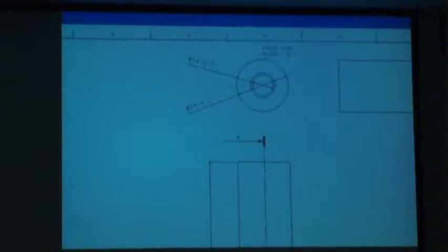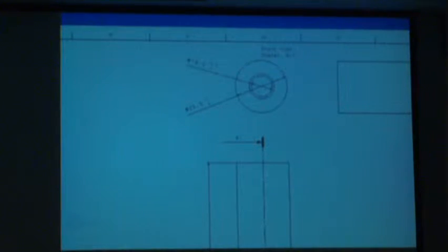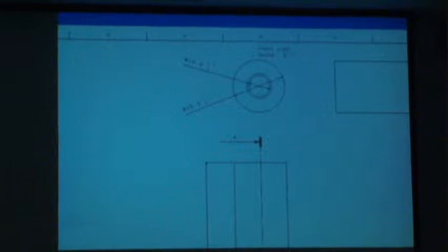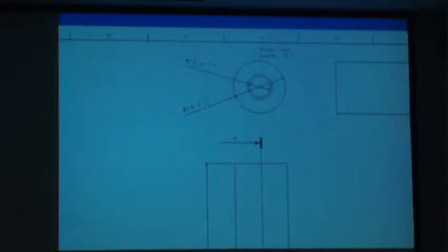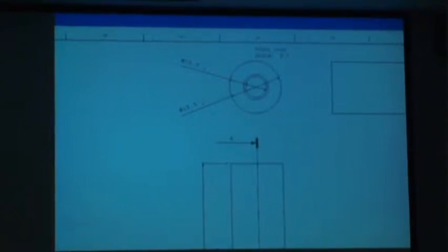And depending on what the part is for, you'll have a different tolerance band. So if it's something like the outer casing and it has no real functional value, it's just for looks, you may have very big tolerances so that fewer of your parts that are made are outside the tolerance band. Whereas if you have a fine precision part that's moving in an engine, you may have very tight tolerances so that it can't move at all outside the functional range. The other thing you'll notice here is there is a scale, so it's a 2-to-1 scale. In this particular view, usually you'll have a scale for the whole print and then scales for individual views if they're outside the regular print scale.